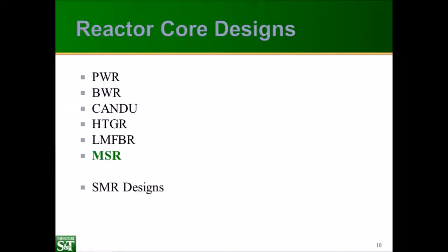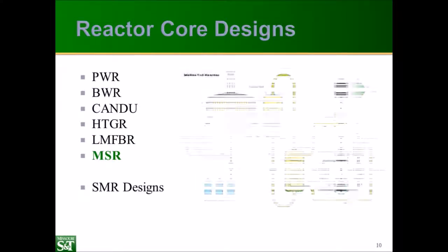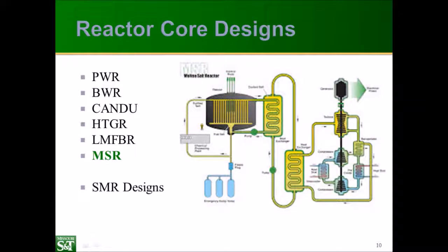Finally, we're going to look at the molten salt reactor. Now, the molten salt reactor, the fuel itself is molten, which eliminates the possibility of a reactor meltdown. And that molten fuel is circulated through the reactor, which is mostly composed of a moderator. So when the fuel enters the moderated region, fission chain reaction occurs, and the fuel itself heats up, and then moves to a secondary heat transfer system, some kind of heat exchanger, that transfers that heat to the power system.